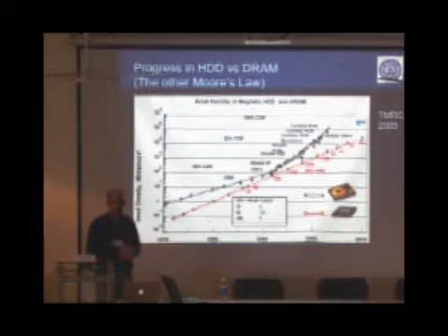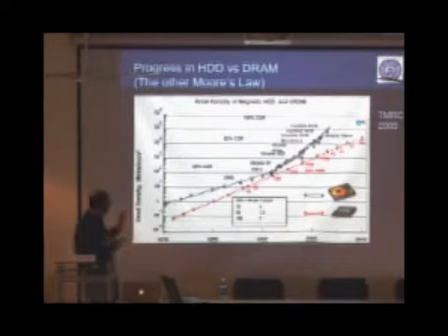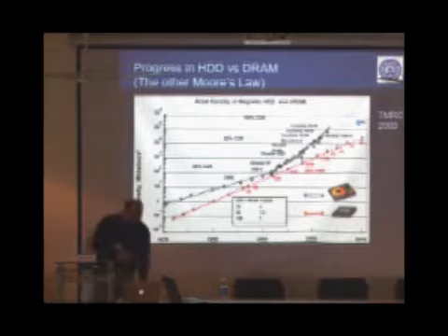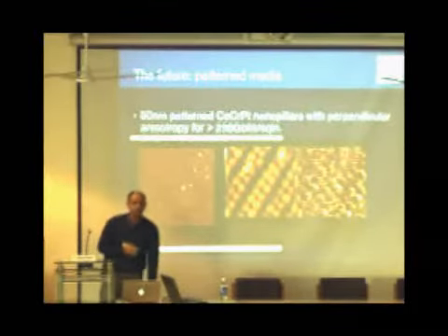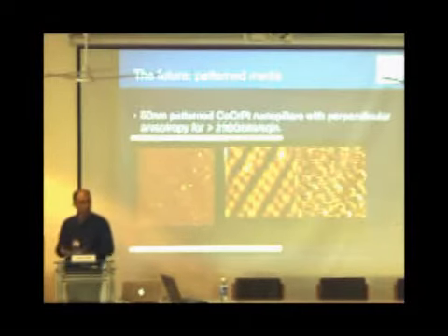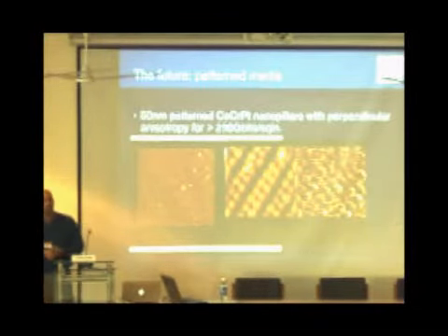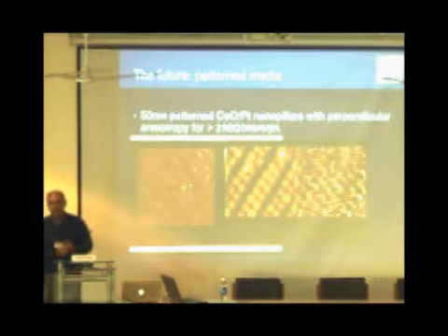The whole lithography shrinks the size of the gate, whereas the functionality of the gate remains the same. However, in the case of the hard disk drive, the advances which make Moore's law possible are different. They are essentially not about scaling by lithography. They are about scaling the read and write head, and about scaling the patterned media.